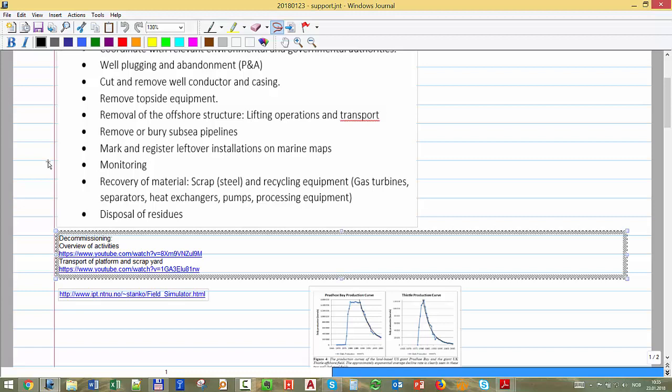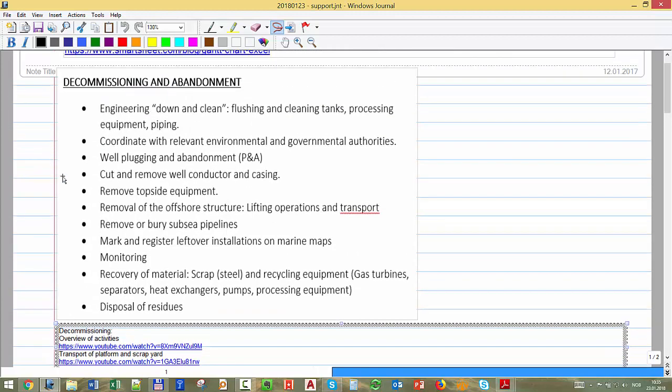No? So who's going to monitor the well after it's plugged? The monitoring depends, but for example, you might put some cameras, you might regularly measure the area surrounding the wells to see if you get some hydrocarbon measurement. You might use boats to sail every once in a while. It depends on what you're monitoring, but usually you're very concerned about hydrocarbon leaks from the wells, and also about the structures you left on the seabed.